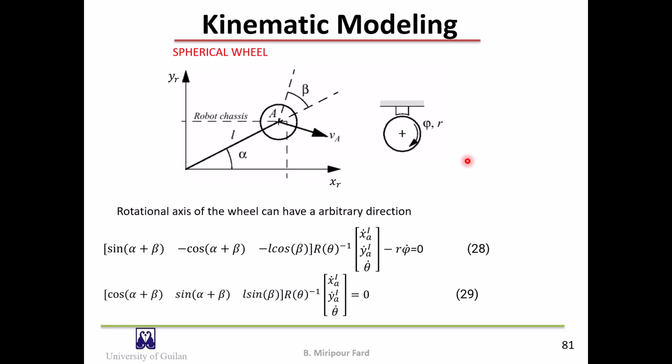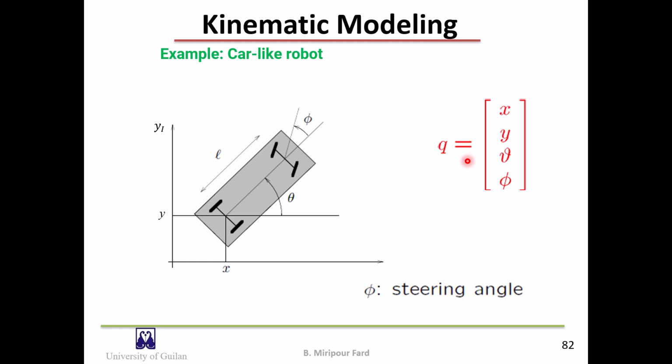So far, we have mentioned the constraints that arise due to the wheels on the robot. Next, we will consider two more examples. The most familiar wheeled vehicle is a car with two steered front wheels and two fixed heading rear wheels. To prevent slipping of the front wheels, they are usually steered using Ackermann steering, as illustrated in the slide.